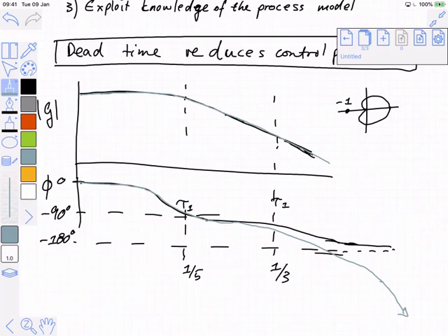But we are moving away from systems that have indefinite stability with proportional control to having systems with conditional stability with proportional control. So from a frequency domain point of view, clearly visible on the graph is the reason why dead time is bad for control. From a stability point of view, more dead time will always move us closer to the instability limit.